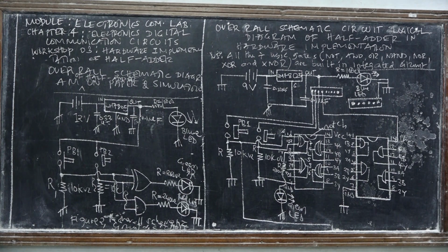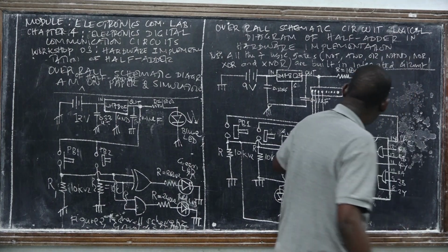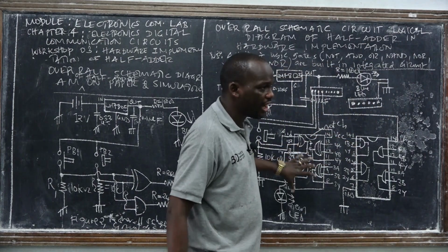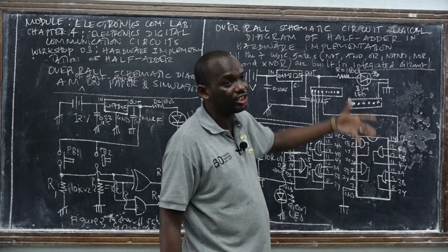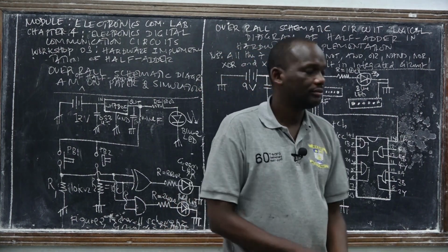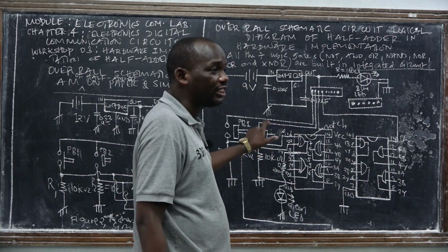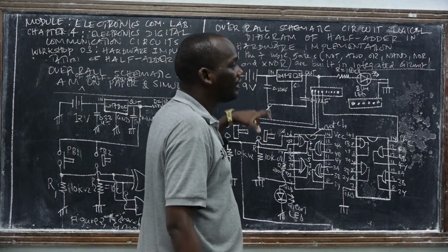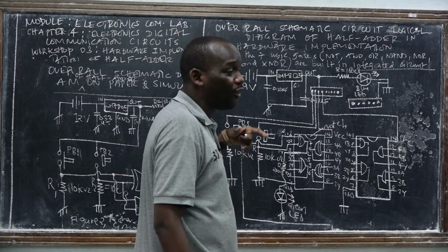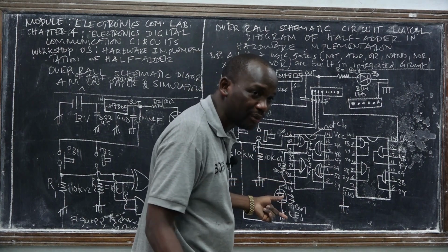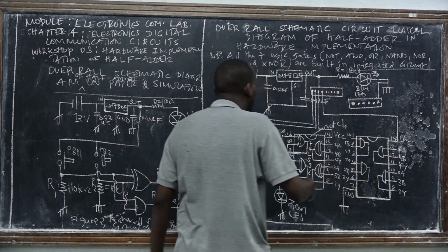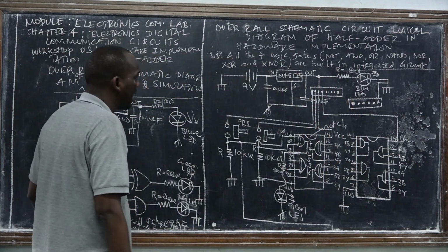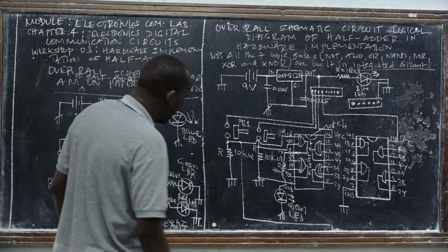Okay? So these are the common pins for four logic gates, or 6 logic gates, or 3 logic gates, or even 1 logic gate. You should not claim that all ICs have 4 gates. No, you should not claim. It's your responsibility to go and check the physical appearance of the other integrated circuit.